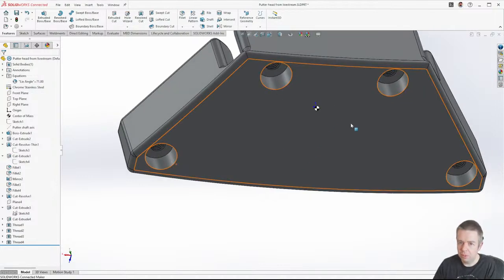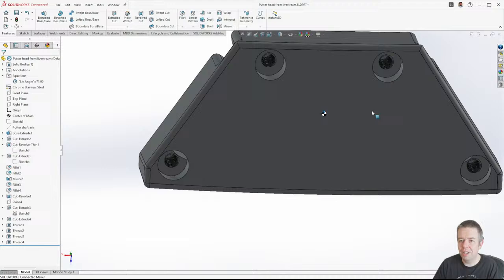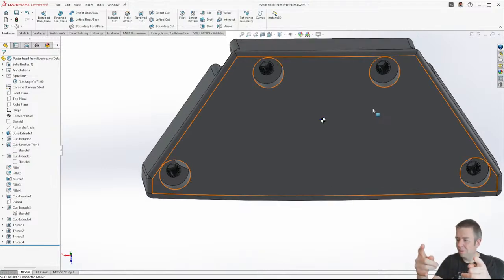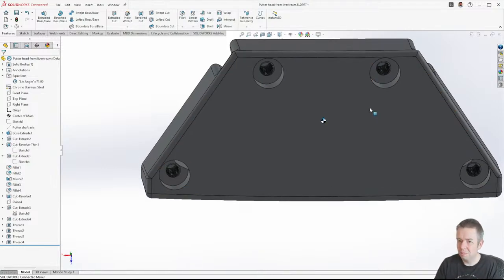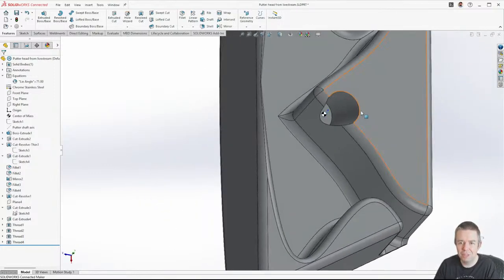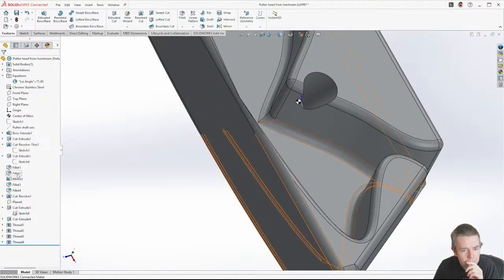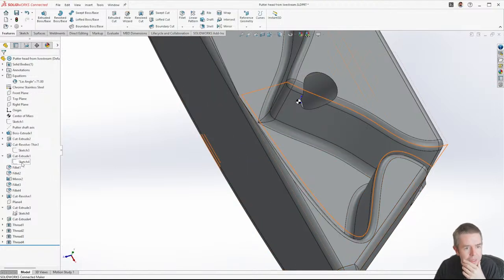And we specifically want the pattern to only work one way round, so that we can't put the piece on wrongly. I could have designed everything so these were a perfect square, but then there'd be many ways to erroneously machine the thing, when having only one way to fixture it is an advantage, not a disadvantage, in my opinion.